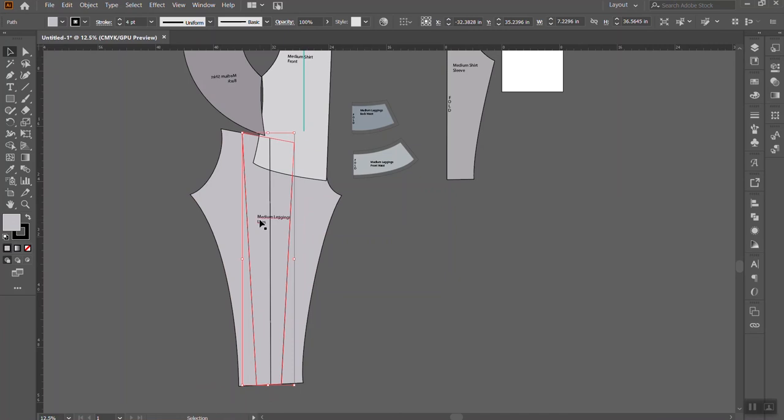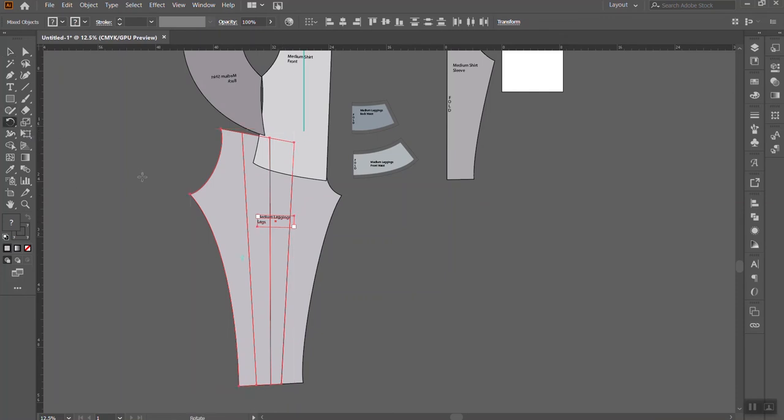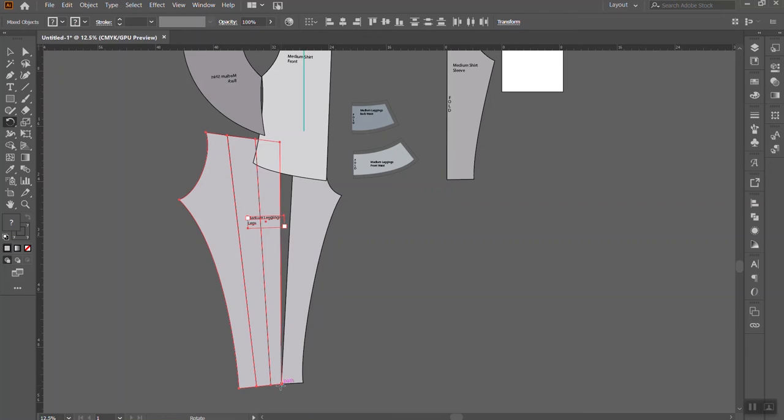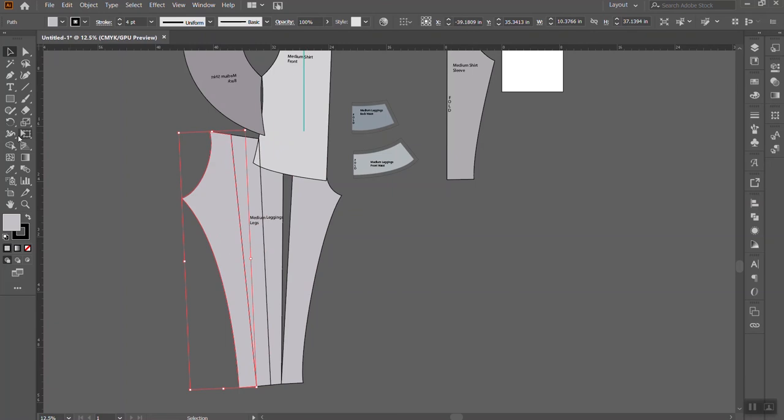So I am going to rotate these, and I can rotate from a specific point by using the rotate tool. So I clicked to place the center point, and now I can rotate these at will. Or rather, I clicked to place the center of rotation is what I mean. So whenever I'm done and I want to rotate this one next, I can come to the rotate tool, and you click to place the center of rotation, and then you click and drag on your shape to rotate it. Like I could rotate it all around that center point.